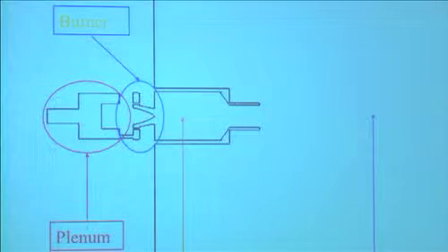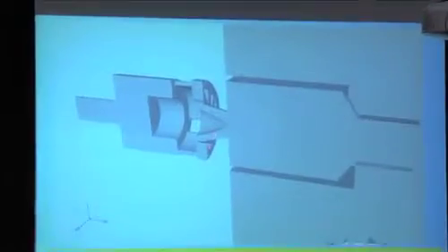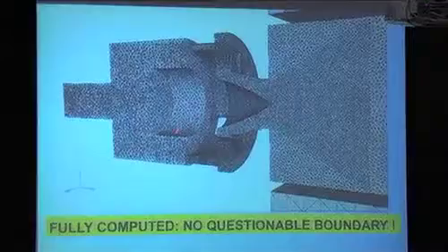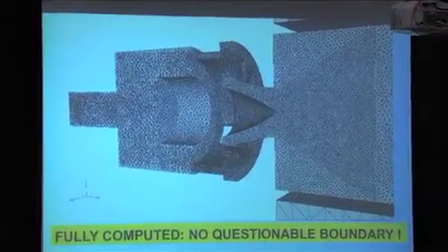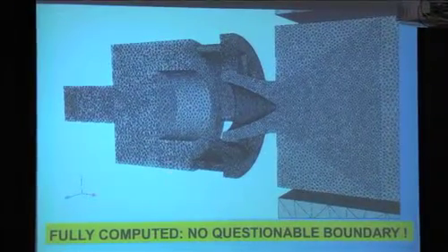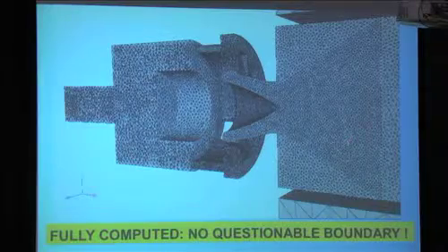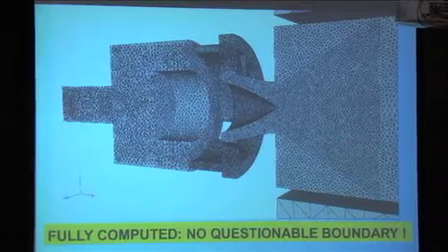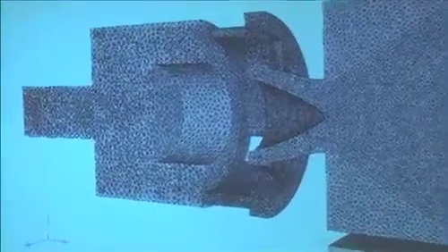We think it's more precise to mesh also the atmosphere, to make sure that we get all the reflection coefficients right here. The mesh looks like this. This is the geometry, it cuts through the geometry. It's an unstructured mesh. To give you an idea of the evolution of codes, this mesh here has about 1 million cells. It was in 2004. Now we do the same computation with 2.8 billion.